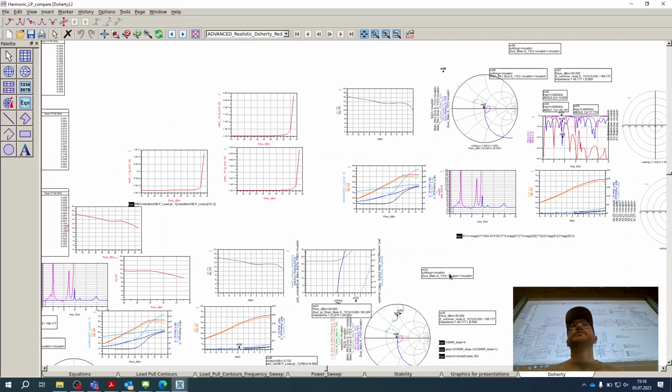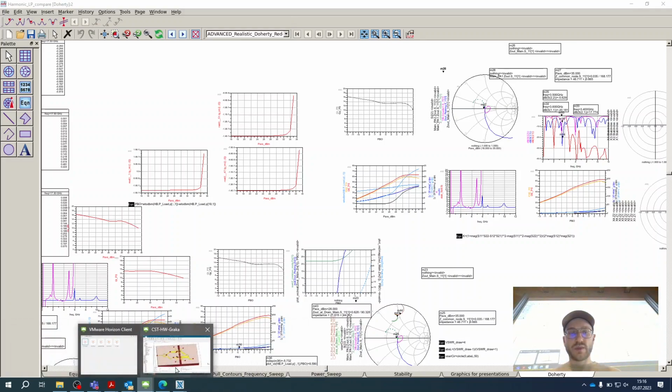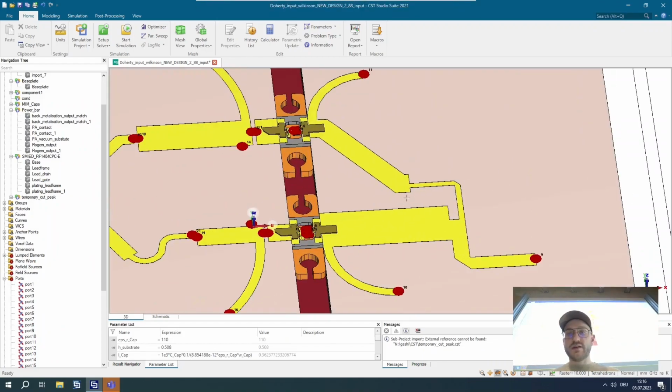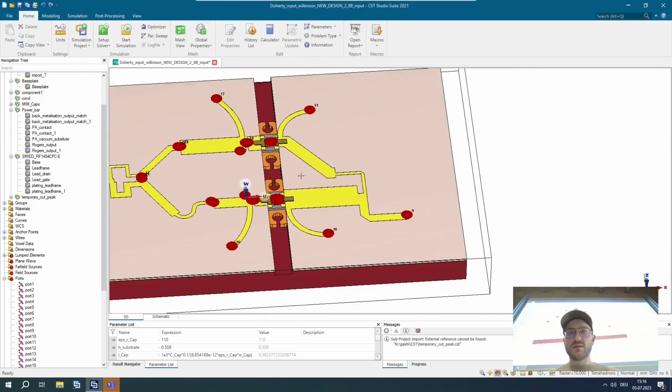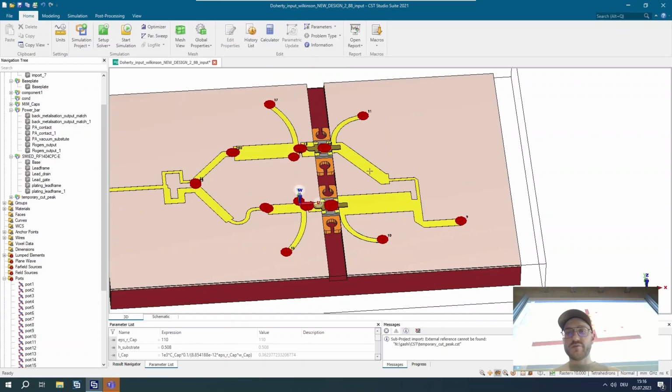It depends on what the thickness of your substrate is, and where you want your application to move towards. In this case, for example, why I used a microstrip line here is that I have a matching layout which has a lot of bends and gets close to the other structures. I'm trying to hit impedance targets and transform to impedance targets and to make it as compact as possible so that I can have a lot of these next to each other processed.